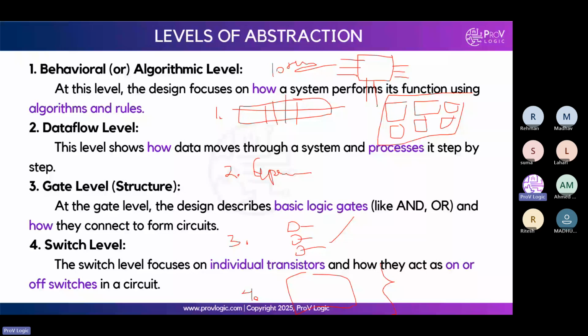Okay, so in the front end, mostly we will focus on behavioral modeling, because behavioral modeling is just logical, just the functionality we can put in the coding. We don't need any gate level circuit. We don't need to draw a number of gates, lakhs of gates. We don't need to draw, just put the functionality. And data flow is also mostly considered, because by using the expression, sometimes we combine both behavioral modeling and data flow modeling. Once you look into the programs and the programming style, you will understand.